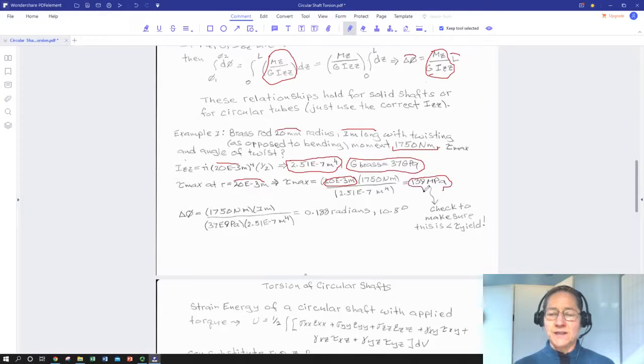And we would take this and compare it to the shear yield stress for the material. So if we looked in a handbook and found that the tensile yield strength of this material was 200 megapascals in uniaxial tension, we would plot that on a Mohr circle and go, aha, the max shear corresponding to that is half the max tensile, and find that we didn't yield.